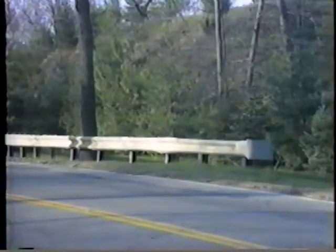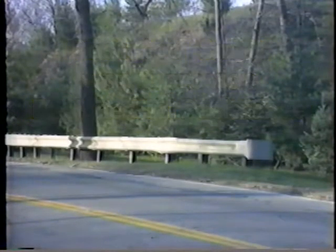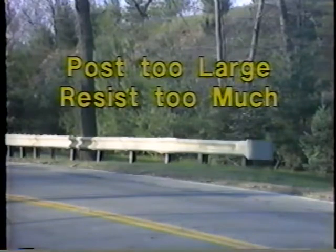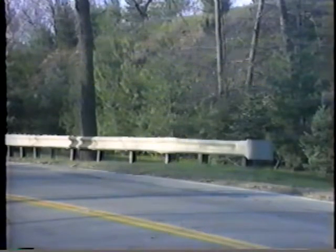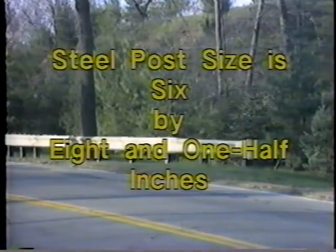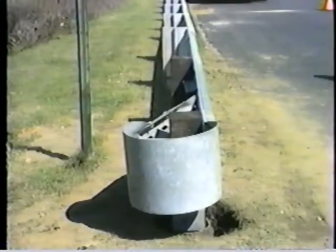Post size and spacing are obviously very important. If posts are too small, they won't provide the designed-in resistance when hit. If they're too large, they'll resist too much. Approved wood post size for the BCT is 6 by 8 inches. Normally a Douglas fir post is used. Steel post measurements are 6 by 8.5 inches. Posts are set on 6-foot 3-inch centers. The first 2 are not blocked out to prevent fouling on impact.